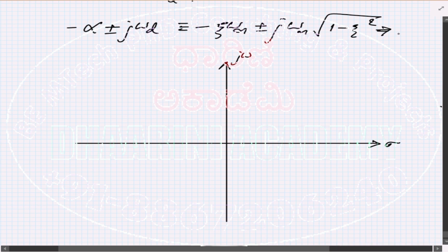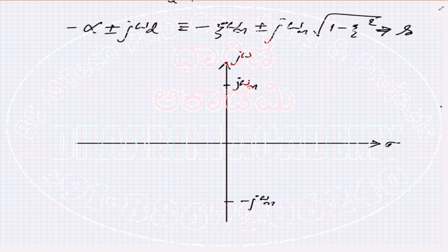So whatever equation you see, this is s, the roots of the equation, imaginary root. So it starts from here. Let me say the first one is plus j whatever, it simply becomes j omega n, correct? And I'll get a minus root, that's minus j omega n. This is when zeta is equal to 0, which corresponds to no damping. The terminology we will discuss once again later, but the damping ratio is 0, so this is undamped. The system becomes one where there is no damping.